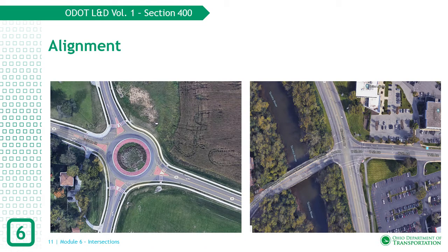The left image is another example of a roundabout being used to improve the horizontal deflection through an intersection effectively. Without this intersection treatment, the northbound and southbound through lanes would have to deflect significantly through the intersection. The southbound movement could potentially conflict with the northbound movements if the driver didn't turn sharp enough to follow the intersection alignment. The roundabout eliminates this concern.